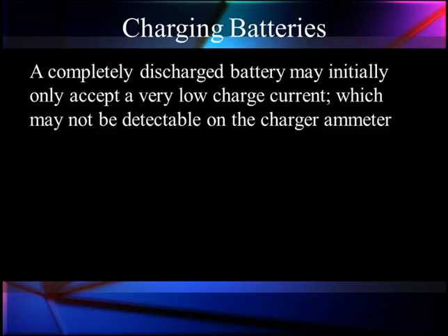A completely discharged battery may not initially accept a charge. It may be a very low current, which may not even show up on your charger ammeter, because it takes a while. As we discharge a battery, we're changing sulfuric acid into water.